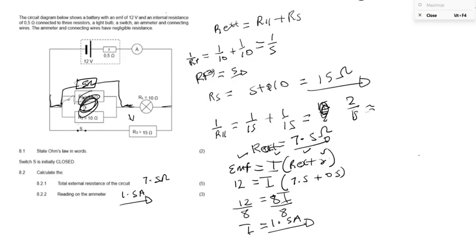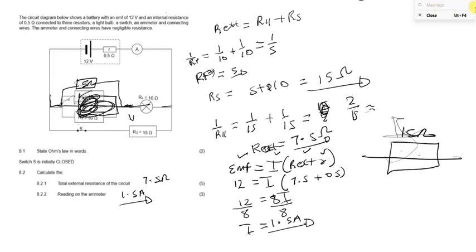So I'm just going to add. 5 ohms is connected with this other wire, so we'll cancel this. You see now we have 5 ohms and 10 ohms. They're in series here because they are in a straight line. So you add them. When you add them, you get 15. Now you have 15, the total overall here. Now let me draw your new resistor. It will be 15 ohms on the upper bridge.